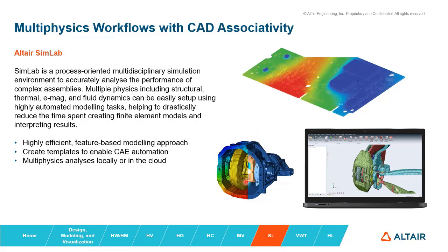tasks. So just talking about these three examples right here, I have my suspension system, most of my parts included here, and I want to verify what is the response of the system to specific loads that is being applied. So I have here, let's say, my upright, my brake disc, and my brake caliper, my wishbones also. And I want to add some inputs such as the braking force or the cornering force or my bump force and verify the response to all this loading. What is the displacement of the system? What is the deformation and the stresses caused by those loads?